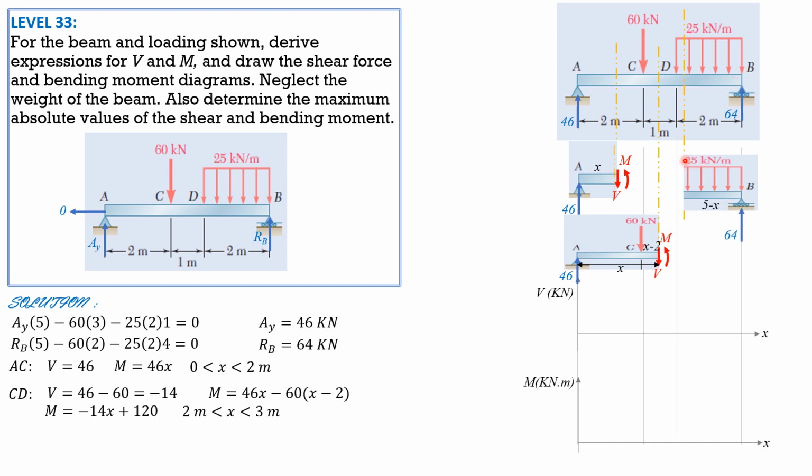So shear is upward this time, positive. So this is 5 minus x because this distance is x. The total length AB is 5. So therefore, this is 5 minus x, as shown in the figure. So that's a positive shear, which is upward. And the positive moment, remember the sign convention, is clockwise at the left. So at the right section, down for positive shear, counterclockwise moment, because this is the right section if you consider A and that section. So first, let's establish the shear equation considering forces to the left.